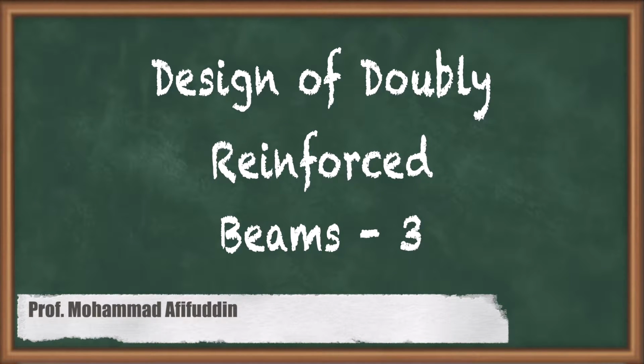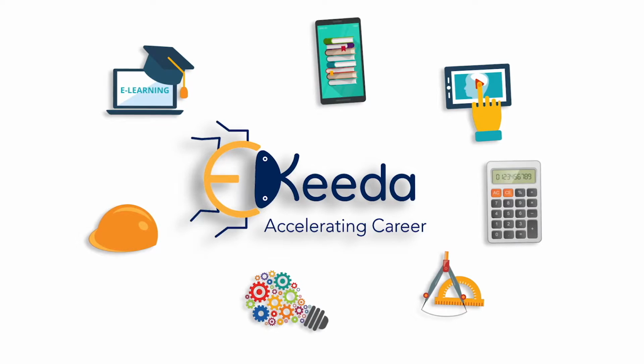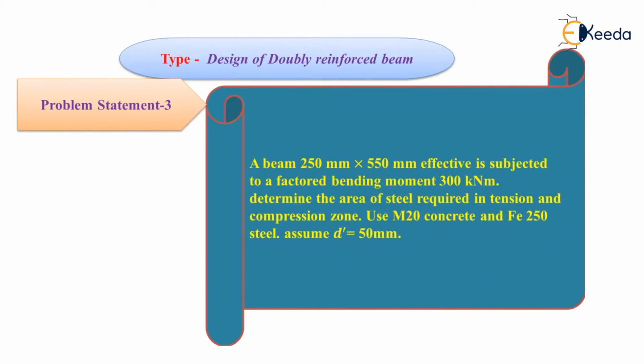In this video, we will see another problem based on design of doubly reinforced beam. So here is the problem statement. A beam 250 mm by 550 mm effective is subjected to a factored bending moment of 300 kN. Determine the area of steel required in tension and compression zone. Use M20 concrete and Fe250 steel. Assume d dash is equal to 50 mm.